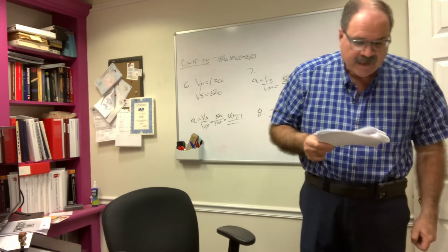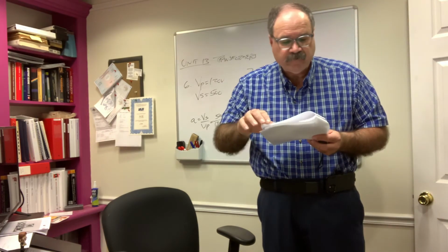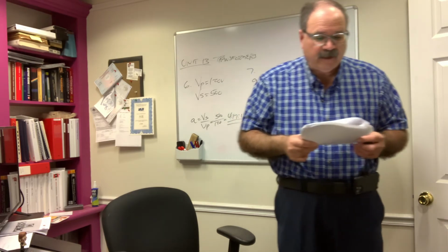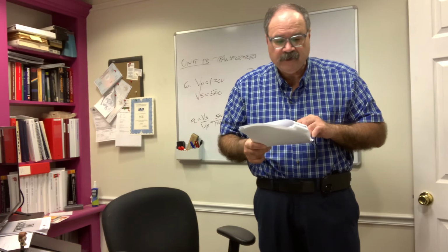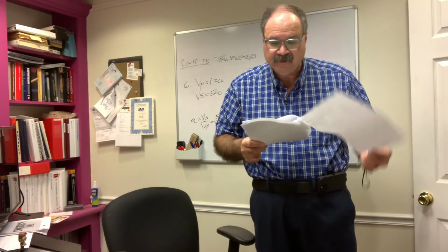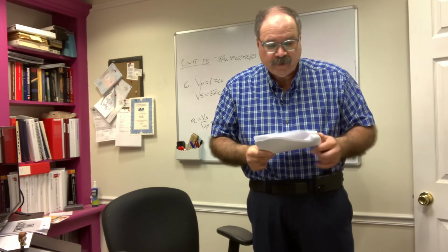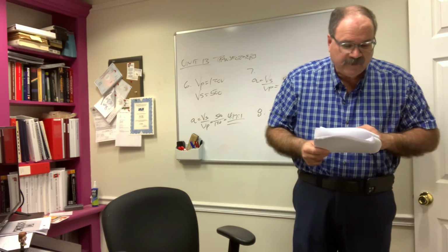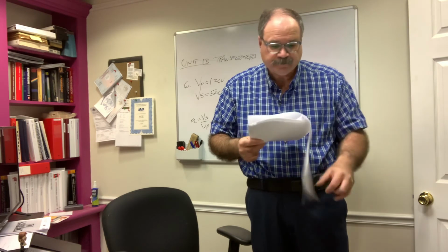Question 9. The distribution transformer changes the high voltage of a power company distribution line to the common 120/240 volts that are used to supply voltages to most homes and businesses. Question 10. Loads that are intended to operate on 120 volts connect from the center tap, or what's called the neutral, to one of the secondary lines.